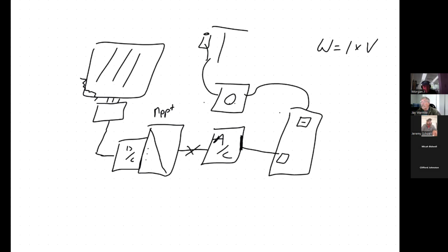The load is what's going to govern how many amps are flowing, up to whatever the maximum the system is designed to handle, at which point a circuit breaker would trip because you've exceeded, or you're getting close to exceeding, the capacity of the wire. So you put an overcurrent protection device in there to keep that wire from burning up. You want an identified, easily accessible point of failure, which is what your circuit breaker is. You can reset it after you've removed those loads. A circuit breaker is just a weak point in the system, and it's designed to fail.